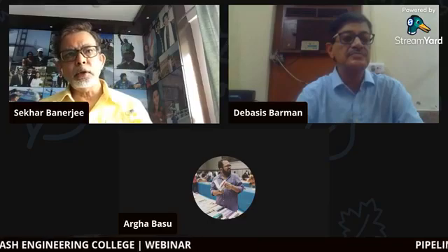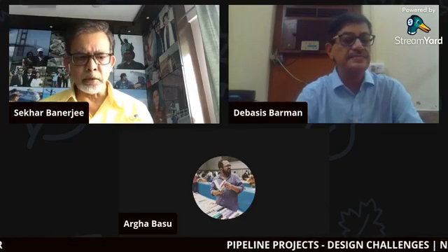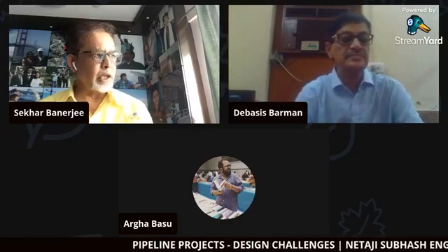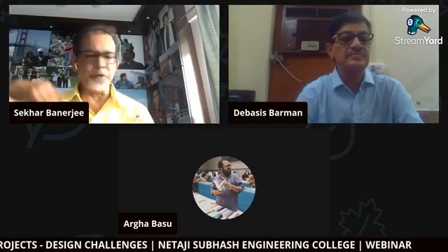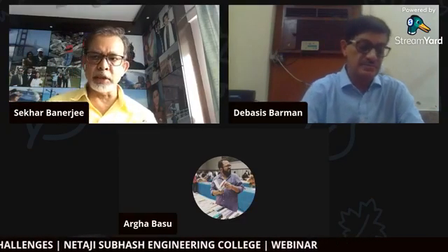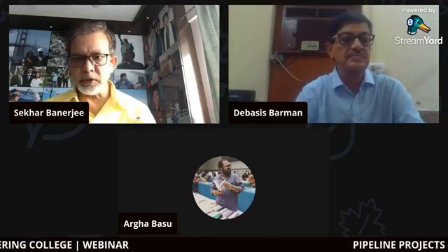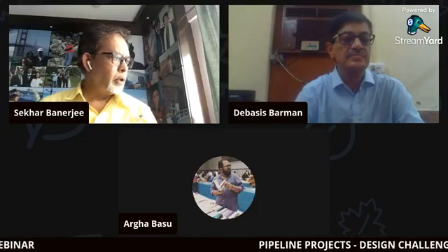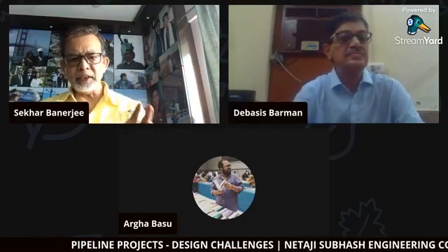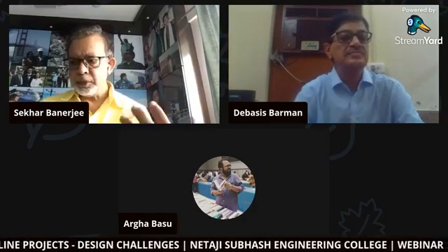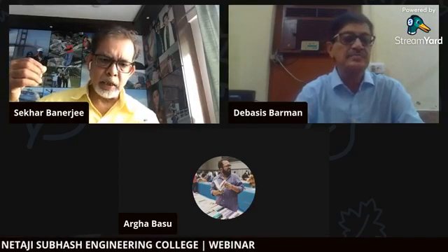For all these items, there are sensors and there are switches. Switches basically give you an on-off type of signal, that it has exceeded or it has not exceeded, like a digital signal. And there are sensors which give you an analog signal. Students must be familiar, at least by looking at it, they should know that this is a pressure sensor, this is a temperature sensor, this is a flow meter, and these are level transmitters.